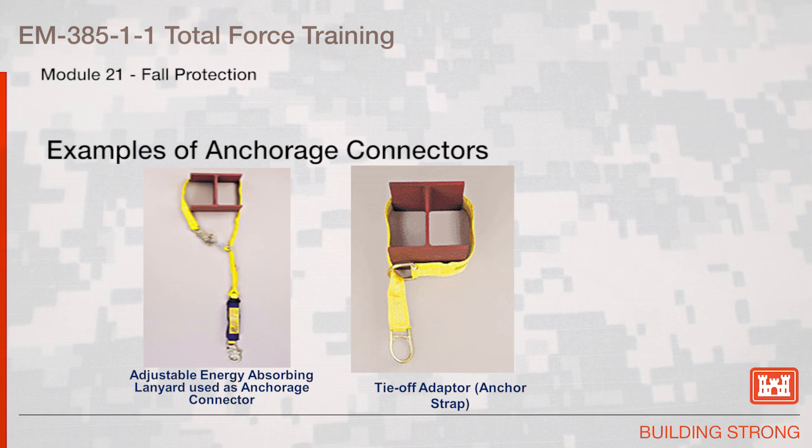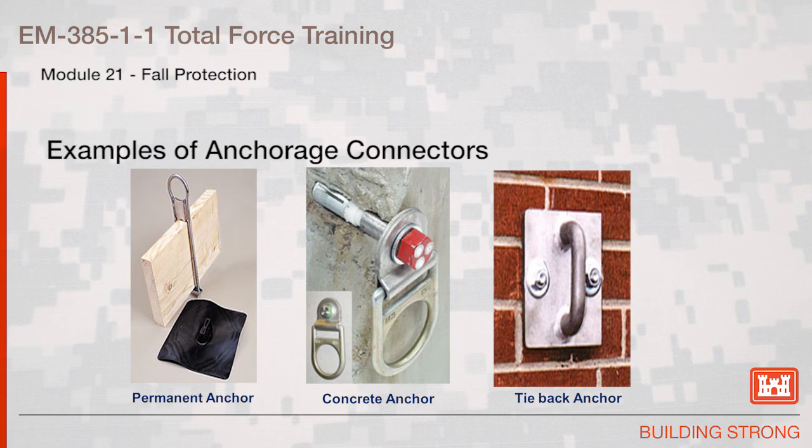These are examples of anchorage connectors. The picture on the left illustrates an adjustable energy-absorbing lanyard used as an anchorage connector. Lanyards should not be tied back to themselves unless they are designed to be tied back onto themselves. The picture on the right illustrates a tie-off adapter, also known as an anchorage strap.